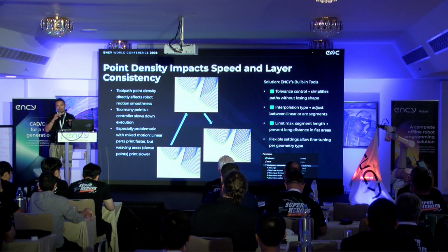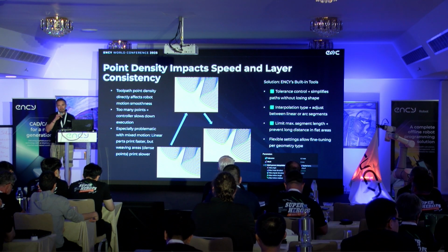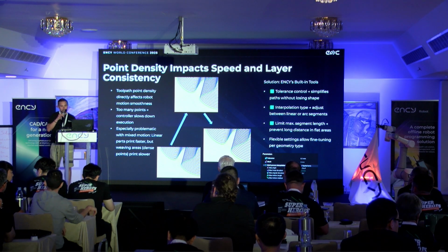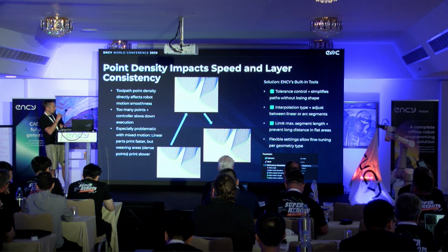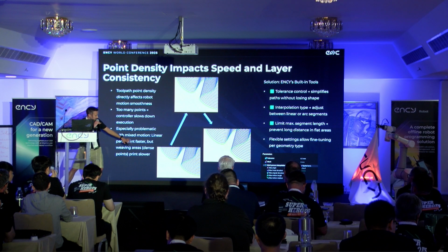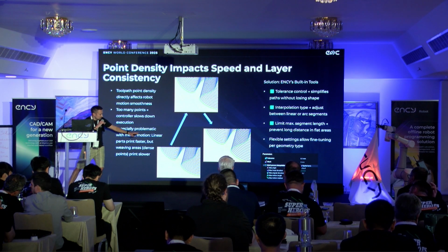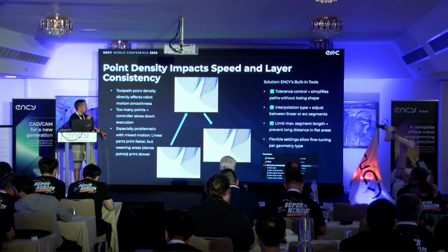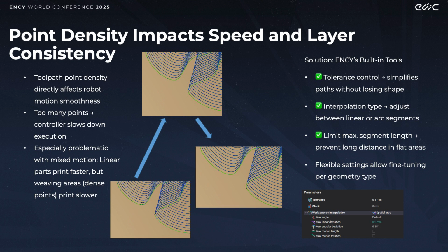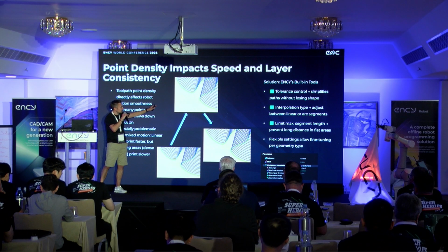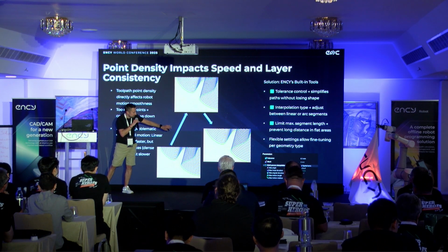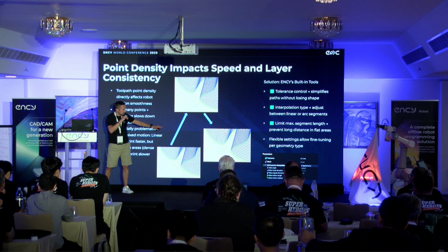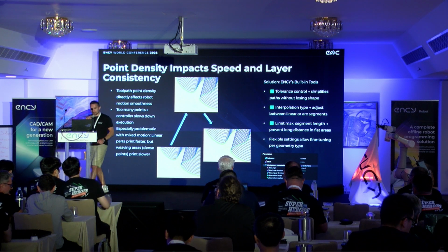But when you play a little bit, 5 minutes with different values, usually we can do instead of this a lot of points here. In this case, the robot is not able to reach the target speed. Then we can try to increase tolerance, fewer points, but still not acceptable. And then going to, for example, spatial arcs interpolation gives us the best result.